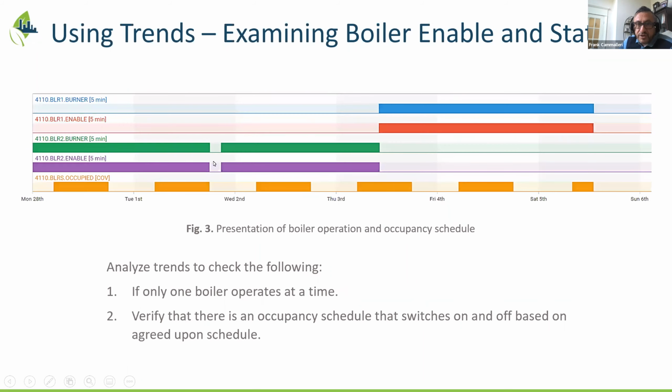And again, this is just another view. This is more digital points, digital on off. So again, just further supporting that only one boiler and burners on at one time. So during this time here, there's only boiler 2 is running, and then this is only boiler 1 again, just to make sure that the boilers are off. And then there was only a small period of time.